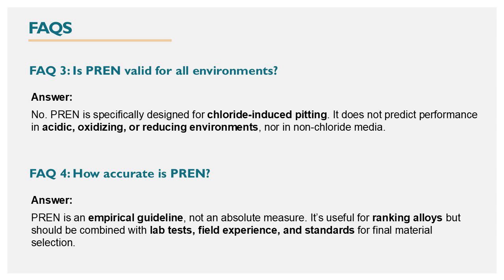Question number 4. How accurate is PREN? The answer is, PREN is an empirical guideline, not an absolute measure. It's useful for ranking alloys but should be combined with lab tests, field experience, and standards for final material selection.